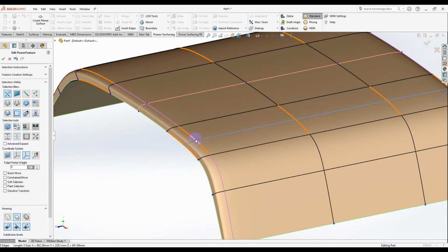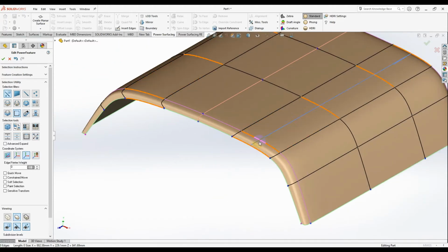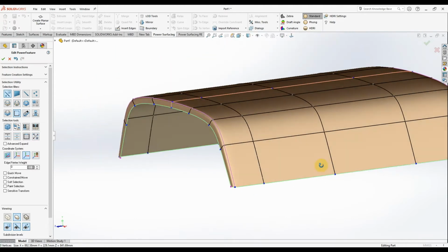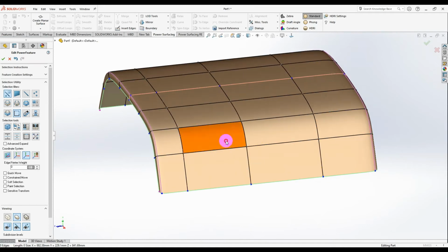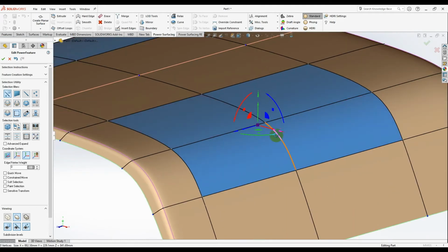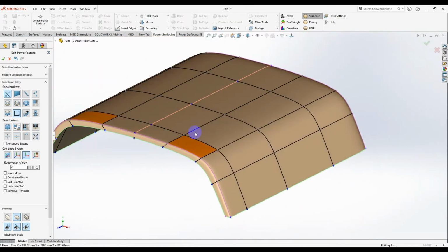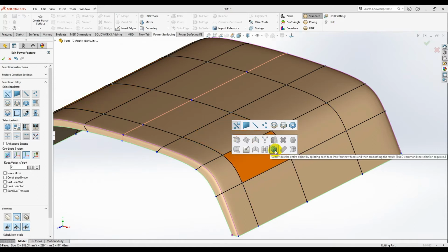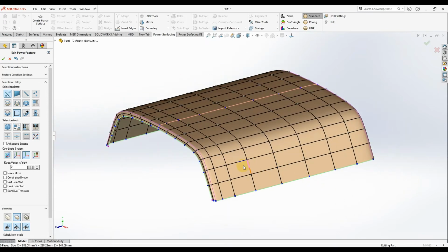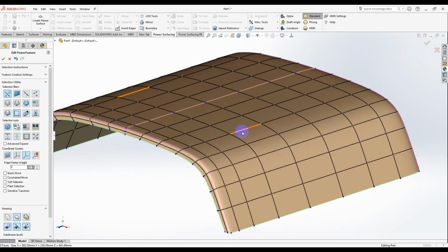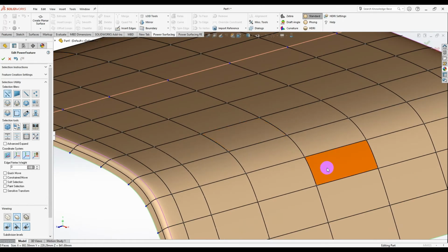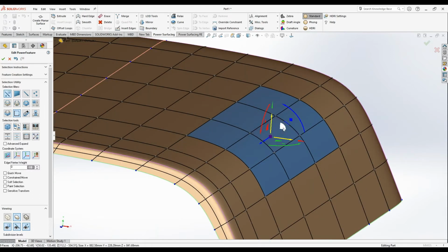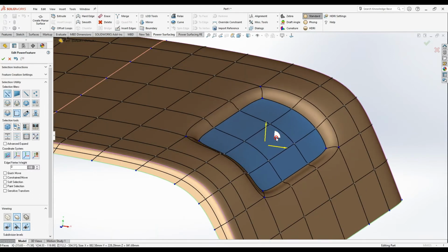I can easily do the same at the other sides. Okay, now I'm gonna click on this one and create a line here. So I just created a line. Let's make some more detail. We can also subdivide it by right clicking on the part and pressing subdivide. I can see that it doubles the faces, the lines and the vertices, so I can easily select more details like this, hold the A key, press and snap.